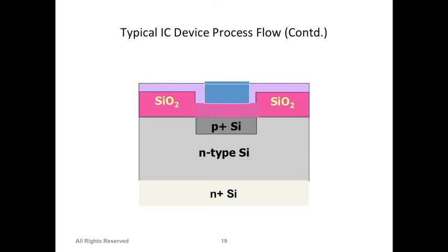HCl, HF, yeah, HF. Okay, we did talk about HF quite a few times, right? So it is HF, which is very commonly used for etching silicon dioxide very specifically. You can also use dry etching, for example, to etch silicon dioxide, but it's not HCl, okay? HCl doesn't etch silicon dioxide. So we use, let's say, HF or any other reactive-ion-etching-based dry etching process to etch silicon dioxide.